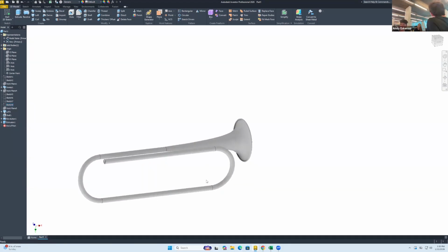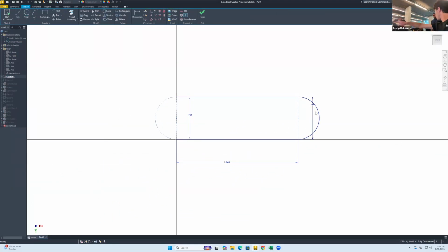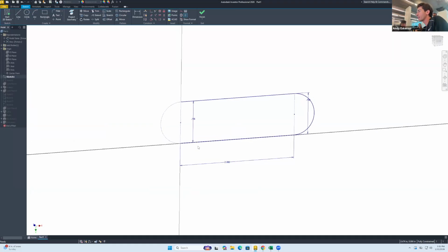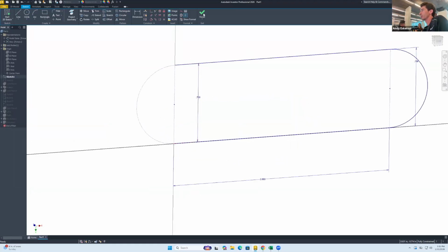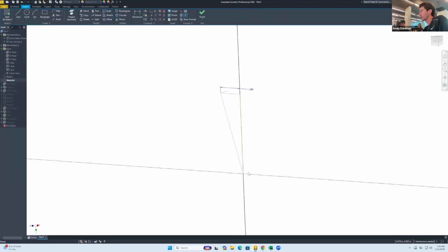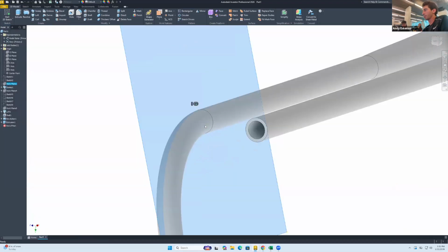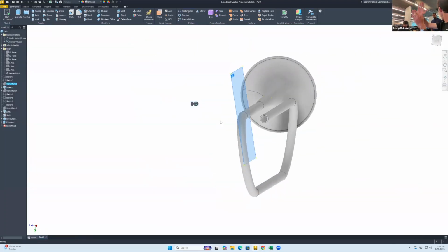Questions up to this point? So it's not as trivial, right, in the end, to do this. So let's rewind for a minute, just so it's clear. We started by doing this sketch. We just drew the profile, and the key was to begin here in the origin. Then we clicked on finish, then we did another sketch that went from the origin, and it just created an angle. Because by having this at an angle, I drew a line that is perpendicular to that one. Why? Because we created a plane right there, a point normal plane that was angled like that.